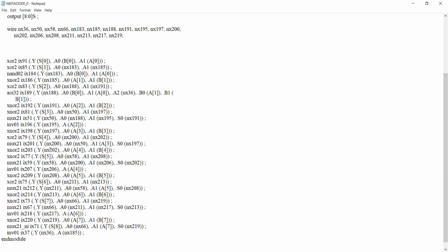for testability and functionality. So after verifying the DFT, we need to insert a scan. In order to perform the DFT, we need to apply this particular netlist file, and then we need to insert the scan chains. There we need to use the ATPGs in order to verify the testing. After that, it will go for fabrication: layout generation, placement, routing, and then fabrication.